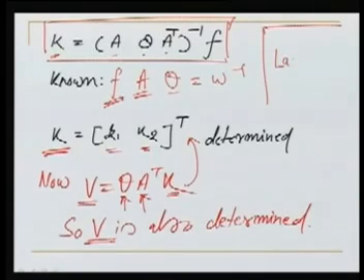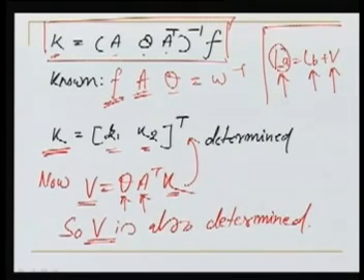The LA is LB plus V. Because V, the residuals, are known, we will add these residuals to our observations and we can find the adjusted observations. So finally, we are able to determine the adjusted observations. In this process, starting from our basic conditions, we could now find the adjusted observations, or we say the estimates of the observations.